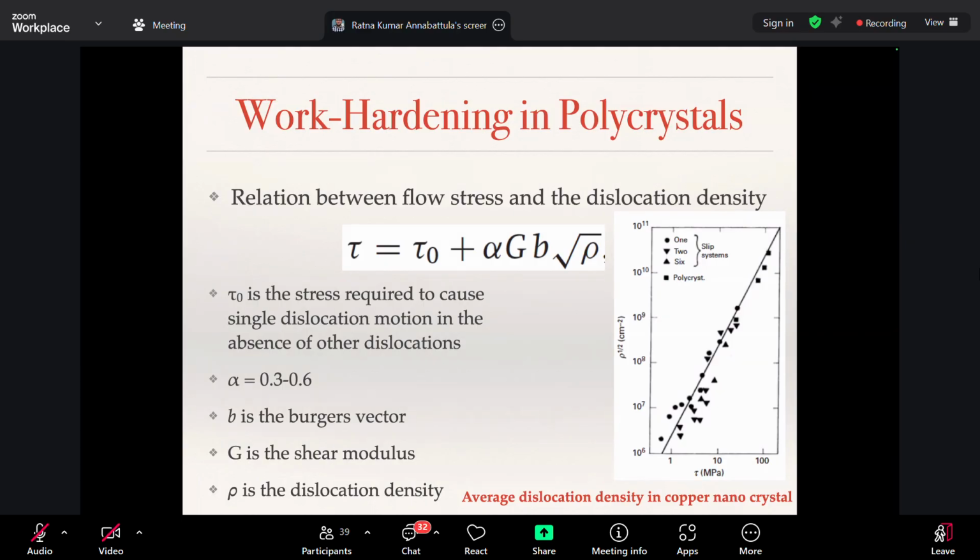As a result, you can have a local stress field that is getting altered, and when the dislocation sees that variation in the local stress field, it needs to adjust to it, and hence it sees a resistance to the dislocation motion. That is the difference between solid solution strengthening and grain boundary strengthening.